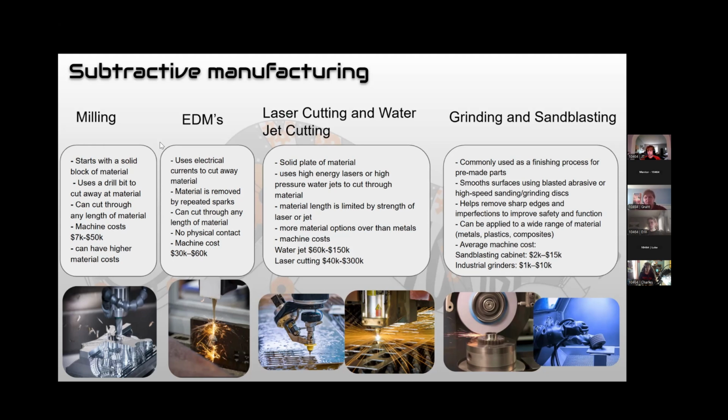But laser cutting and water jet cutting, those can do a lot of types of plastics, or a good amount of types of plastics, a lot of metals, and some wood as well, depending on if you get the right cutter. Once again, you gotta look at your specs for your machines, but these do a lot of different types of metals. You would need a higher end machine to start doing titanium and AR500. But for aluminum, metal, plastics, all that, those would be great for that.